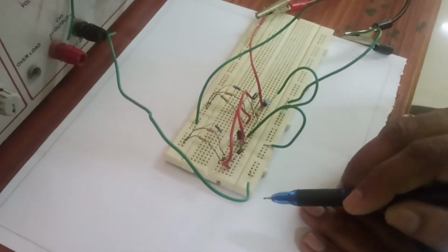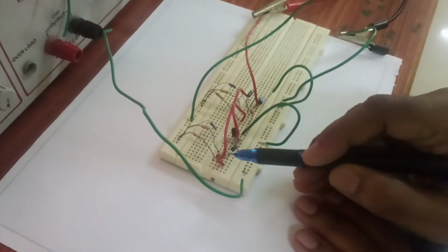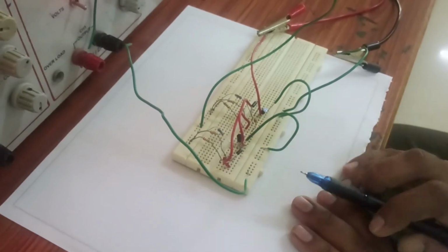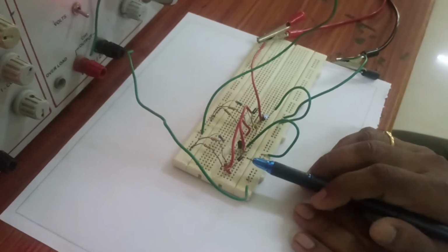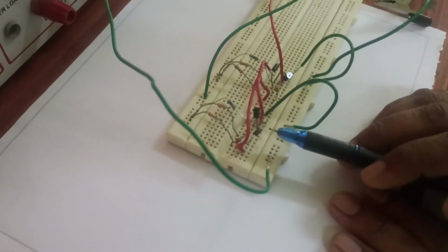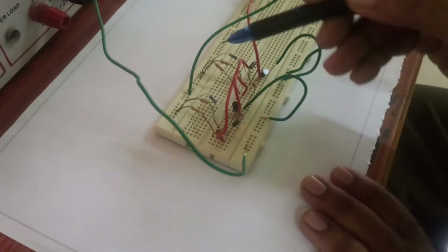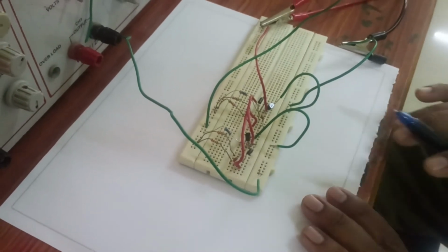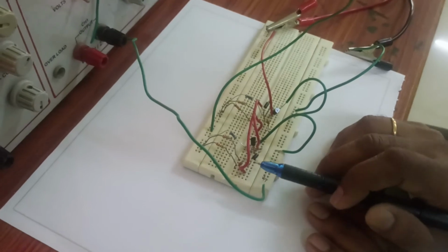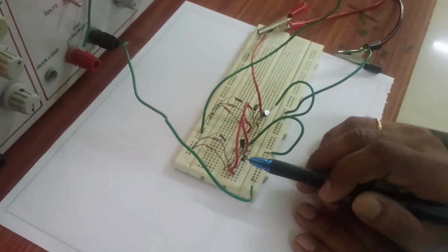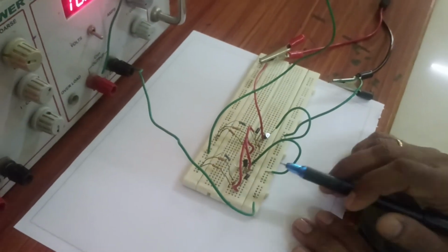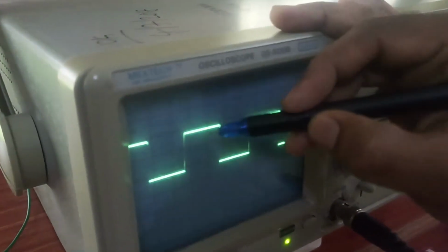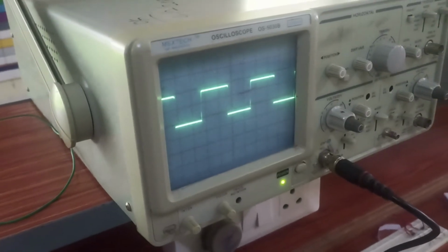In the circuit in the last lecture, the collector current flowing from the resistor went to the capacitor for charging purpose, so that rounding was there. Now if you connect a diode like this, the current is not taken from the collector; instead it is taken from somewhere else, the other resistor in the circuit diagram, the 2.2 kilo ohms. Therefore the loss we saw because of the charging of the capacitor is not possible in this case because of the reverse biased diode. Therefore we are getting a square wave. The curved rounding is now eliminated, as you can see here.